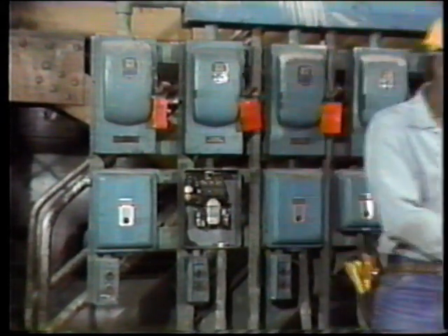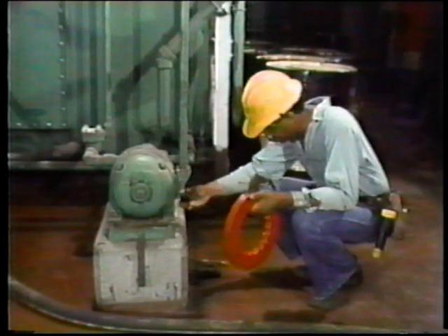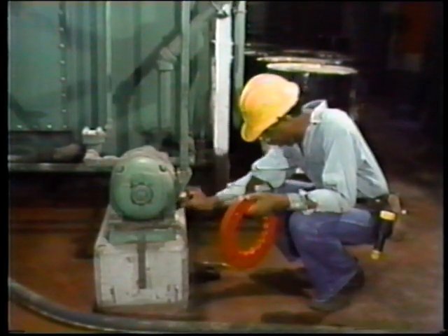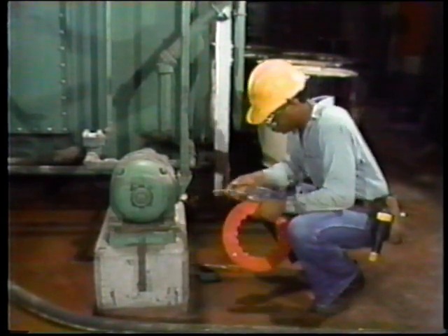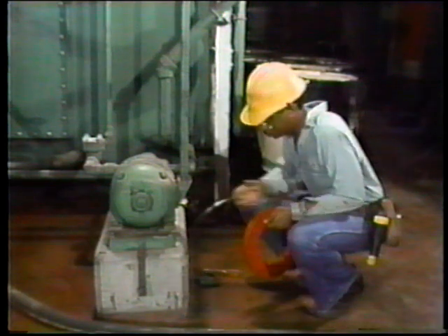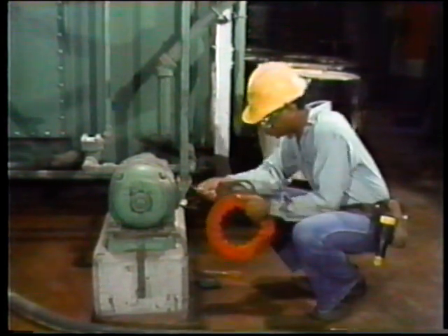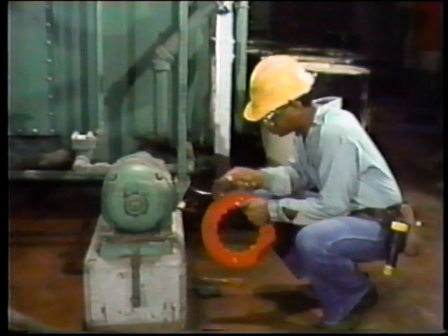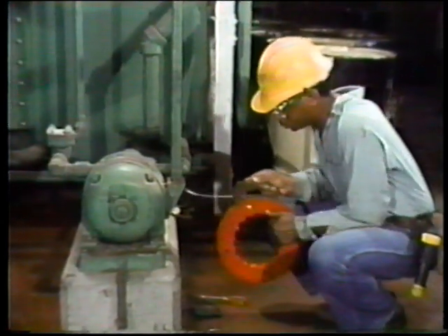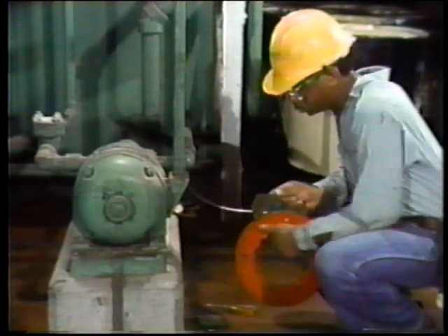Bill has to pull the conductors through the conduit. He'll use a fish tape to do it. The fish tape is a stiff wire that's usually contained in a plastic reel. First, Bill will run the fish tape through the conduit starting at the motor and work back through the conduit. That'll make the job of pulling the conductors through the conduit less difficult. It's easier to feed the conductors into the conduit downward, and it'll give him leverage when he pulls them out at the motor.